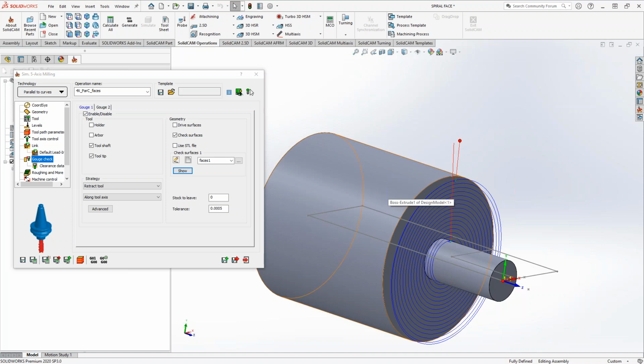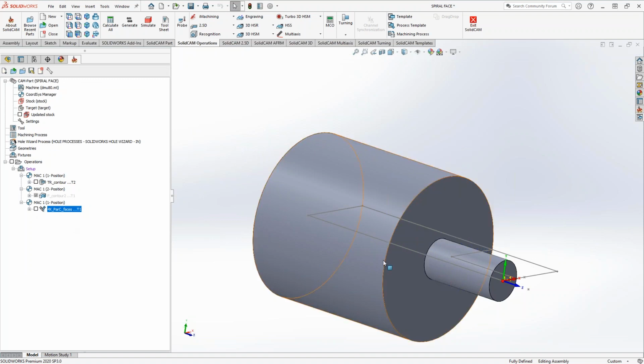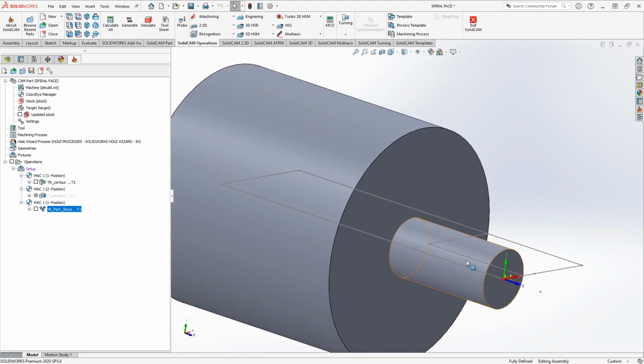Now, if there was a radius down in the corner, we could tackle that as well. And that would be pretty much the exact same tool path as what Mark already has done. We would just pick that drive surface of the radius down there. So if there was a radius drawn in there and we did a flat end mill, and then we wanted to come back with a ball end mill to finish that off, you just pick that chamfered surface as well as the circle for the drive curve and do the spiral working its way down that way as well.